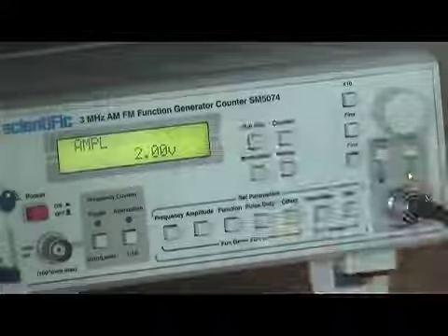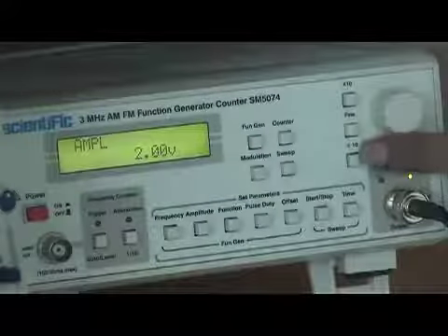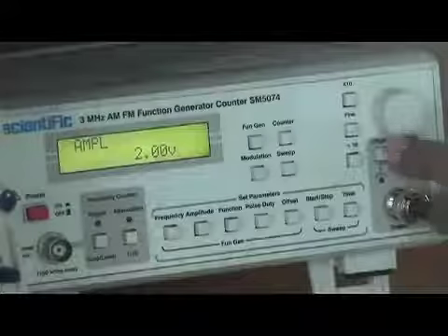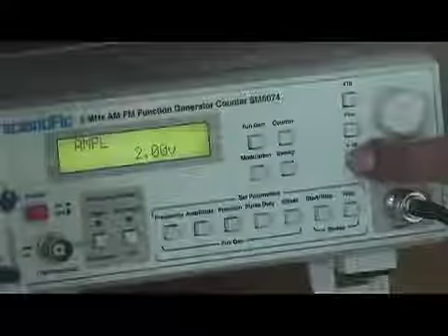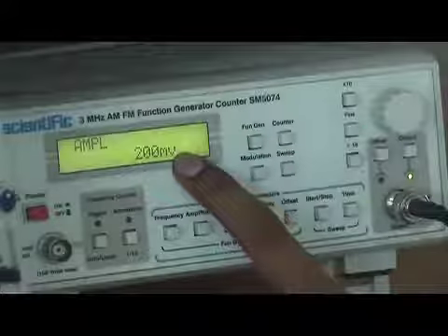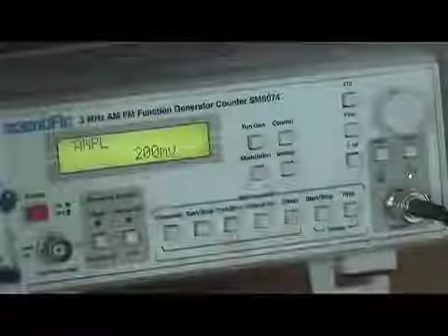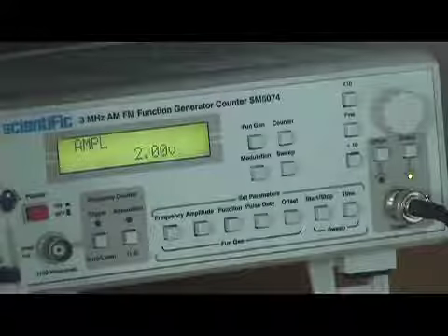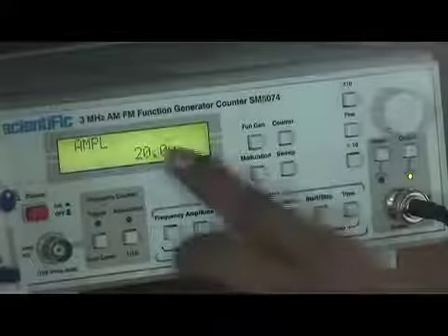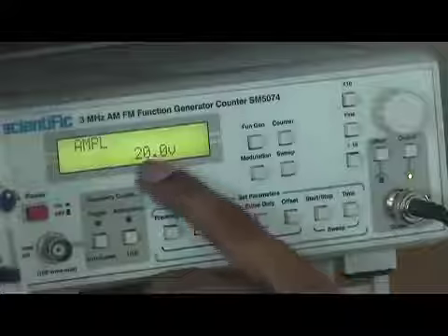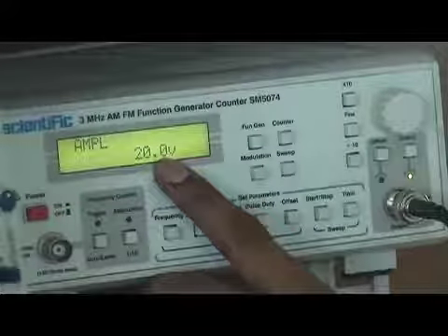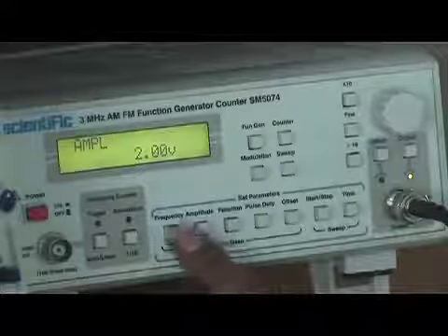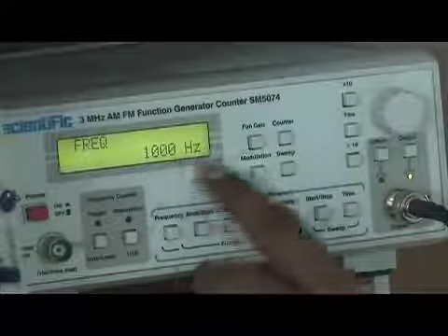If you want to make this unit in millivolts, you have to divide by 10 or multiply by 10. So these two, either divide this by 10 or multiply it by 10. If I divide it by 10, now you can see your unit became millivolts. Now let us come back to volts when I press this times 10. When I press this times 10 one more time, you see the point moves one more times 10. So right now let it be the same amplitude, 2 volt, with the frequency 1000 Hertz.